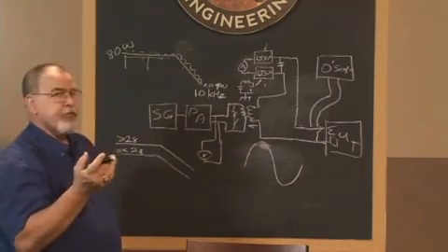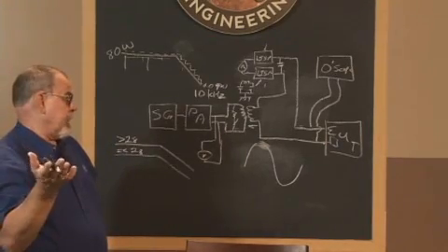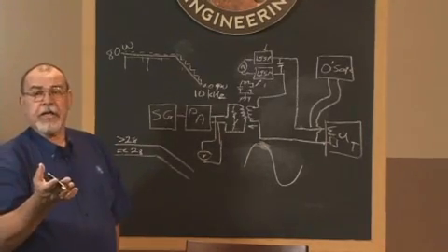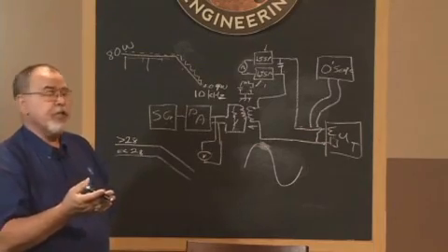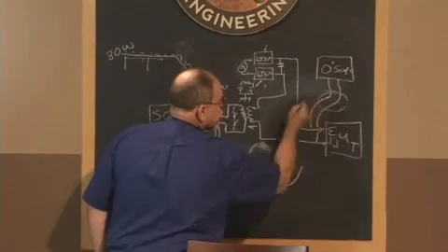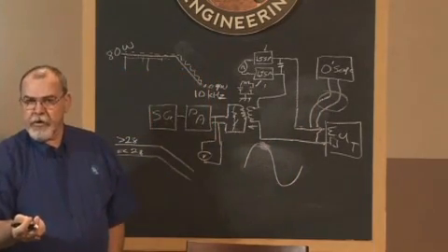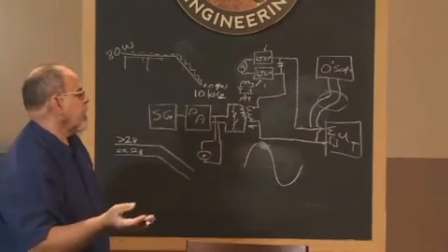There are some filters available. You can look up some elements. There are articles about filtering and things like that for oscilloscope measurements, where the filter goes into the oscilloscope circuit and takes the 60 hertz out, or the primary power out, whatever frequency it is.